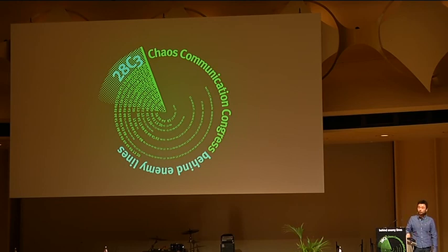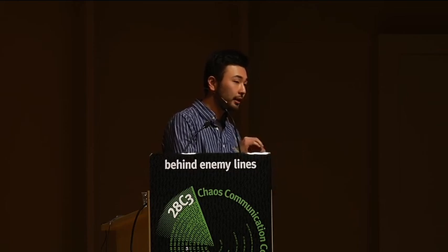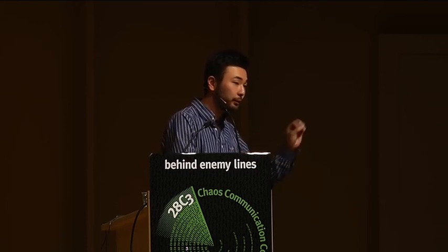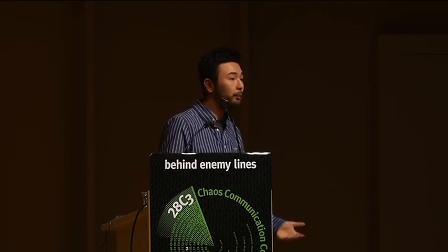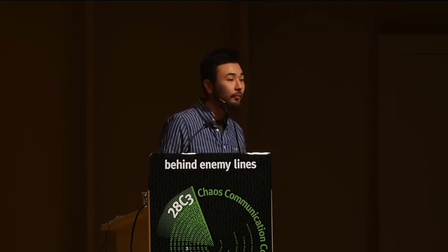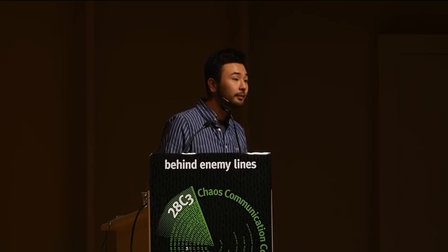Yeah, so you must write your own stereo algorithm for that. In Kinect, the projector position and the camera position are calibrated to each other, so you can't remove them. But yeah, if you have your own stereo algorithm, I think it might work. But is it possible to get the raw data from the infrared camera out of the Kinect? Yeah, it's possible. Okay.